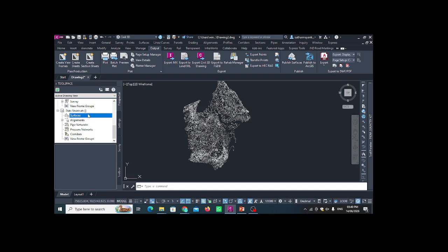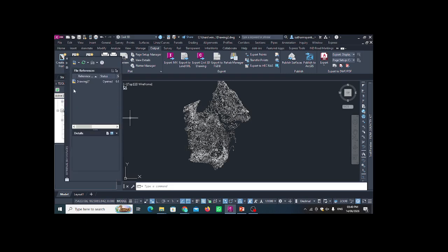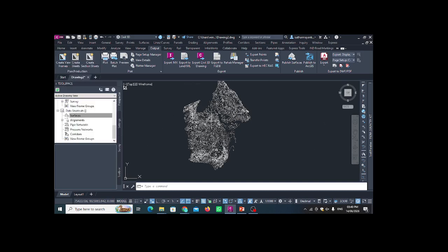So when we create the files, we can save them as a PDF or DWG drawing, like an AutoCAD 2D drawing, and then we send them. Then with the help of the Xref, we can import that file. If you find the Xref here, you can see. So if we have any drawing file, CAD file or whatever the file, we have to open here and we can see the file here.